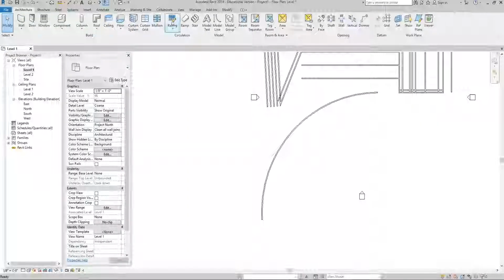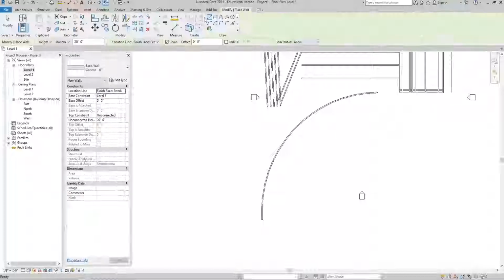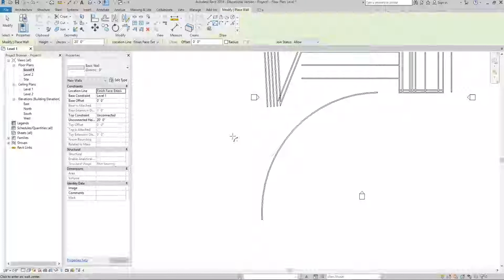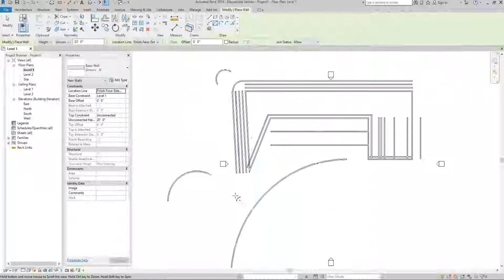And then we have the second one, which I feel is even more difficult to generate, which is the center ends arc, right? So this one really relies on object snaps, and it wants you to specify the center of the circle the arc is based upon, and then draw the other points. So here's the center of my arc, click, click, click. It kind of goes opposite of what you'd think, right?